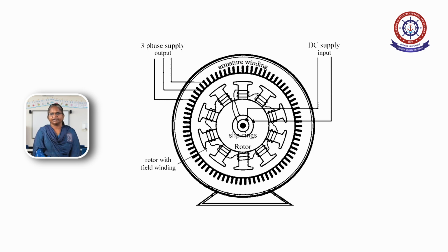The stator of an alternator is not meant to serve as a path for magnetic flux. Instead, the stator is used for holding the armature winding. The stator core is made up of laminations of steel alloys or magnetic iron to minimize the eddy current losses. When compared to a DC generator, the alternators have a stationary armature winding.